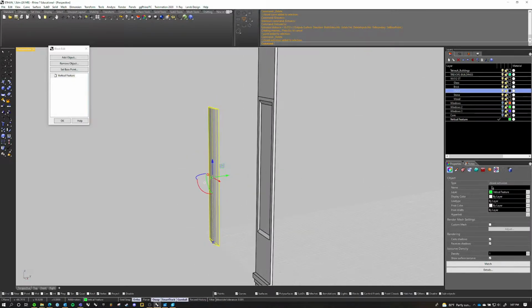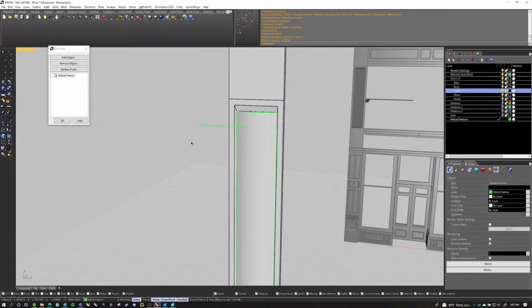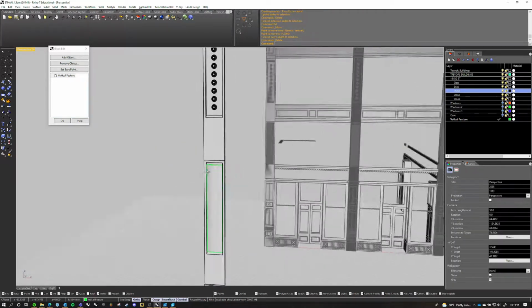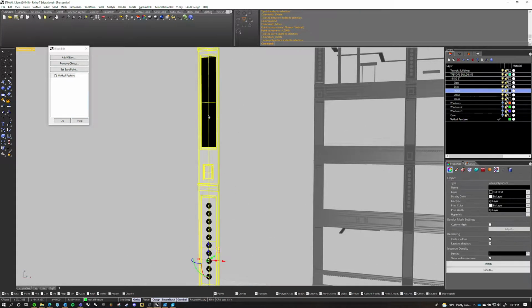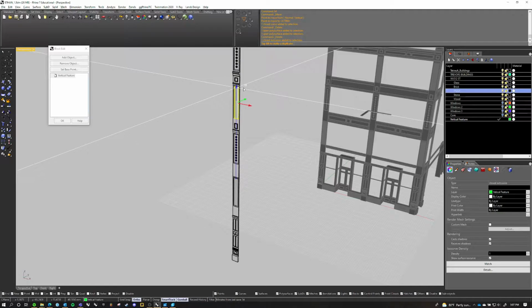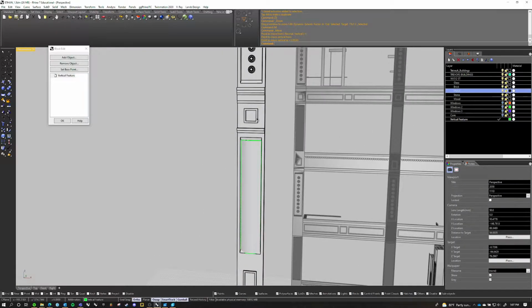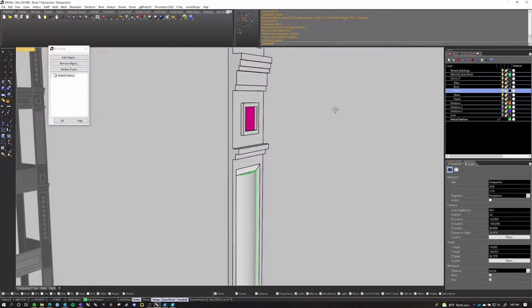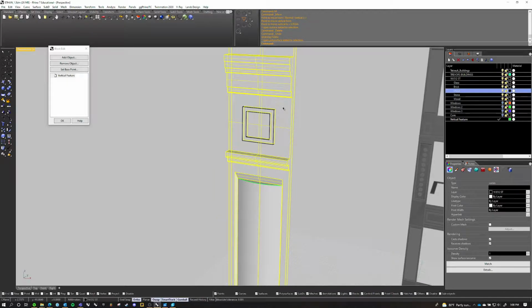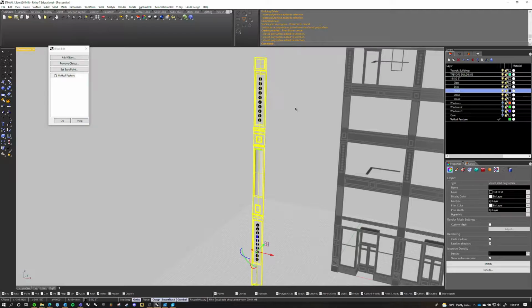Now that should be a solid. It says closed extrusion, so that's good. And move that back to there. And then that'll solve the problem for all of these, which is good. Move V, midpoint to midpoint. That's probably causing problems right there because those aren't joined. So I'm going to join those. Same with down there. Oh, no, that's good. And so now you can see it says closed solid poly surface, which is exactly what we want.